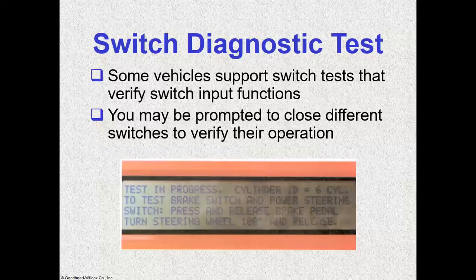Right there and then you will know if it is the switch itself or a component. For instance, we flip the switch for the headlights using the scan tool. You probably will hear the relay click, right? And once that relay clicks and the headlight doesn't come on, chances are either the headlight is faulty or the wire leading to it.